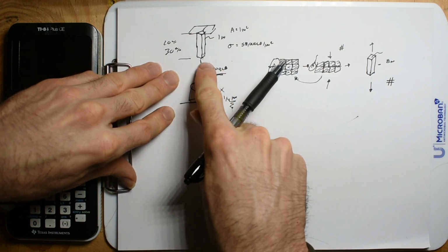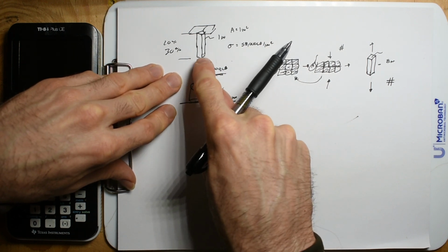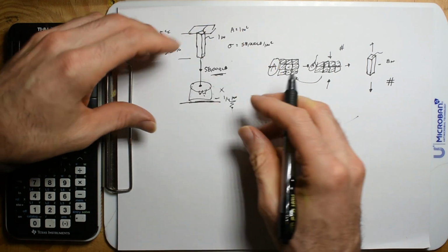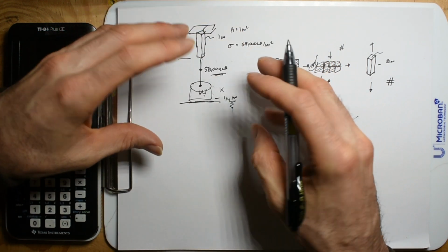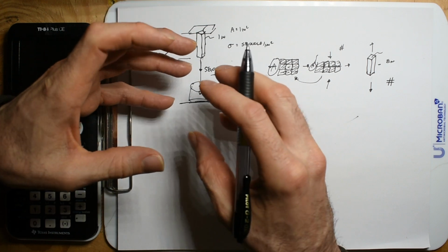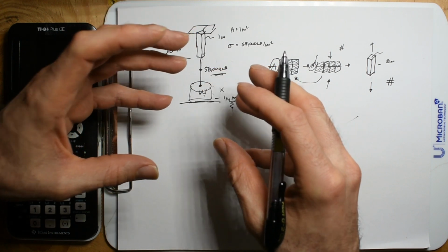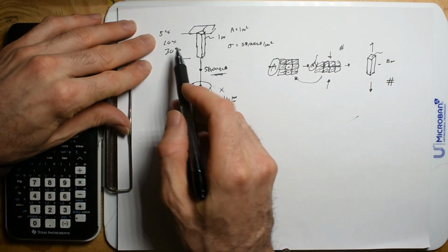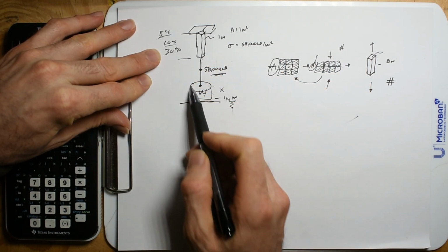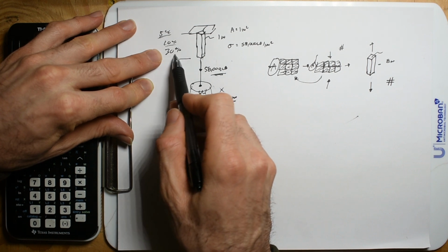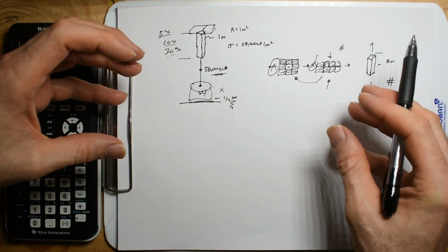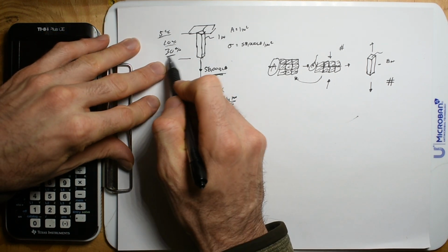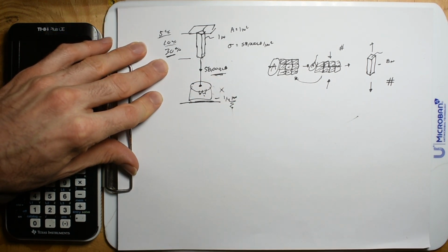So that's one of the aspects of material mechanics: any chunk of steel, well, 5%, you know what I mean? If I have a bolt, bolts with threads, man, they have such inconsistency. But if you have just a steel bar and you're pulling on it, you should be able to pull 5%, 10% fairly easily. You could lengthen the steel bar 30% before you got 2 pieces of steel bar. So steel can get pretty taffy.